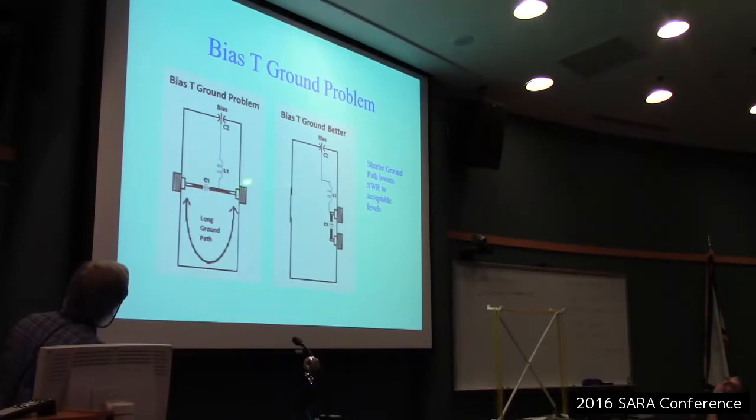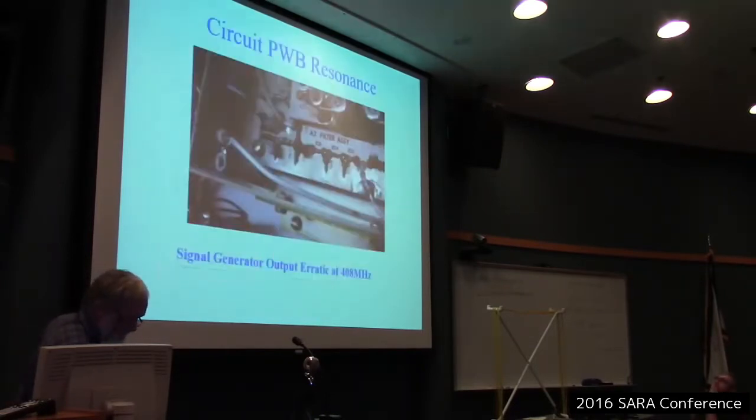And on that one, I had the thing in hand. I removed that connector and just put a piece of copper shielding tape over the hole there to cover it up. Drilled another hole, mounted the connector right next to it. Capacitor down close there. So first capacitor, because it's close, it makes it closer to 50 ohms impedance over this little piece of effective transmission line here. And the ground path's exactly the same length. And all of a sudden now I've got something where the signal very easily goes through there. There was hardly any disturbance at all. It was just removing a connector. Keeping the ground underneath the signal path is a very important issue.